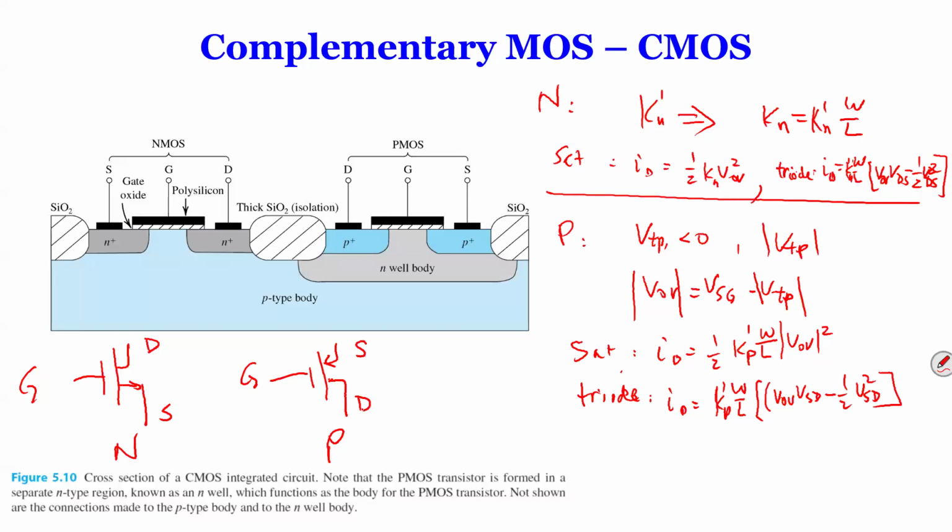It is a little bit difficult to say, but sometimes, for example, in this case, we can apply a positive voltage here, but we can ground this. So we can ground our gate, but this will still have current. But in this case, you cannot ground your gate, unless this is a negative voltage, otherwise you cannot ground this one. But if this is a ground, this has to be higher. So gate voltage has always some value, right? So there are different applications where you might need PMOS or NMOS.